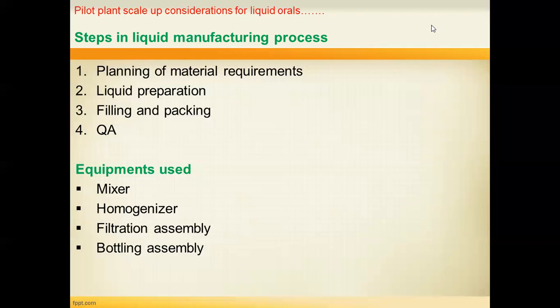In the case of emulsions, various mixing apparatus play an important role, because the globules should be completely dispersed, the oil globules in the water phase. So you need mixing, homogenizing equipment in process, and the final product filters, screen, pump, and filling equipment. Consider the volume of your overall phase, the phase viscosities, and the phase densities. These points are all very important according to the dosage form you prepare.